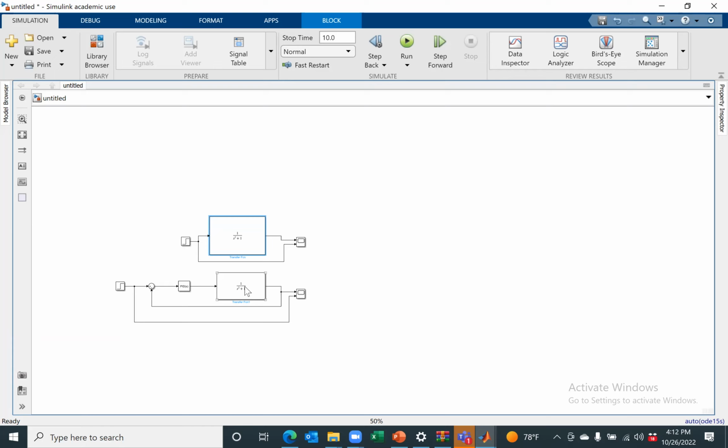And that would actually destabilize the system. That is integral windup. So integral term is used when you are very close to set point. I control is never used if you are far, far away from the set point. If you know for the fact that you are very close to the set point, that is when the I term in PID is turned on.